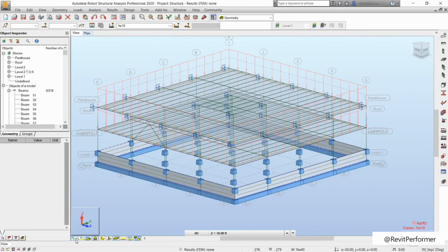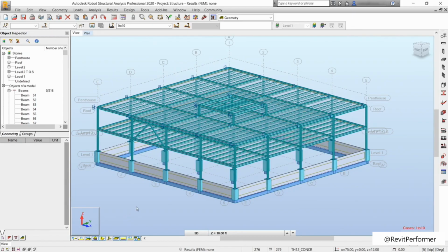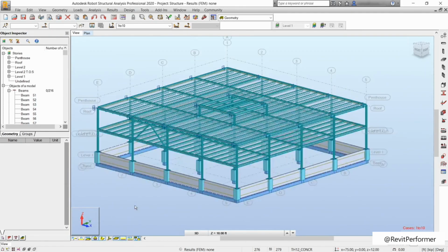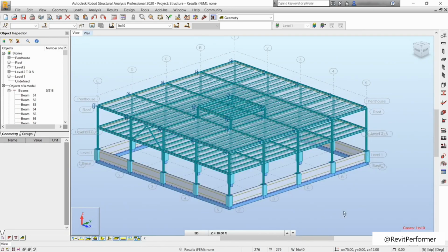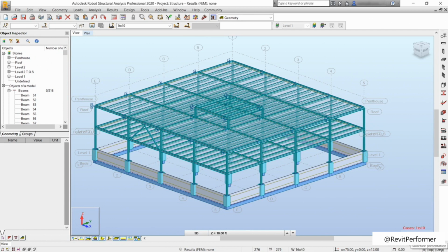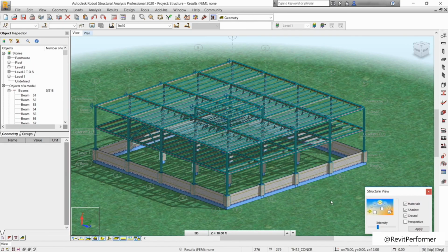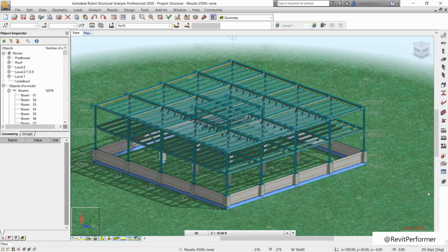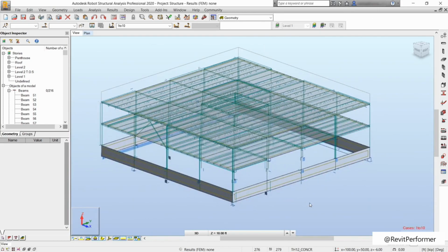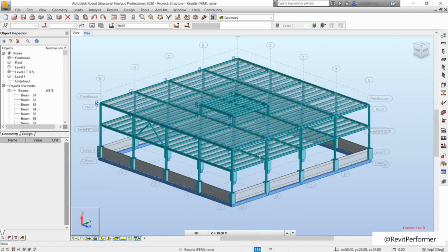Now looking down here, we'll see what is basically the view control toolbar in Revit. So for example, if I want to see the section shapes, I can click on this icon right here, and we can see those section shapes. There they are. If we come down here, we can see our view settings. So if we click on, for example, structure presentation, it takes a second. Now it puts grass down there. I don't think we want to go barefoot on grass, so that's kind of a funny presentation. Also, it's very slow. So close out of here. We don't really want to see that. And really, to be honest, having this stuff showing up is kind of off-putting.